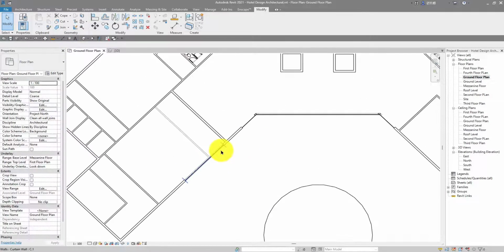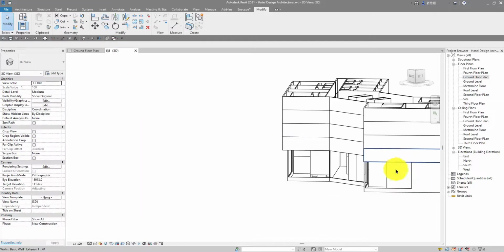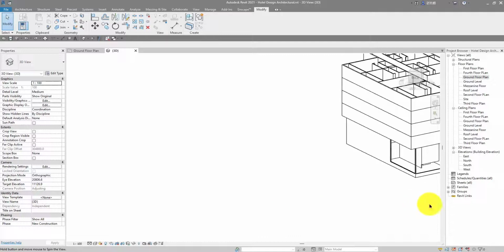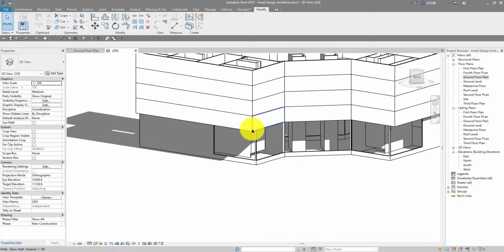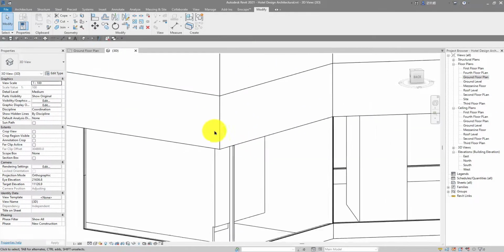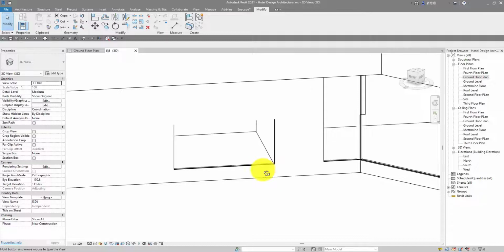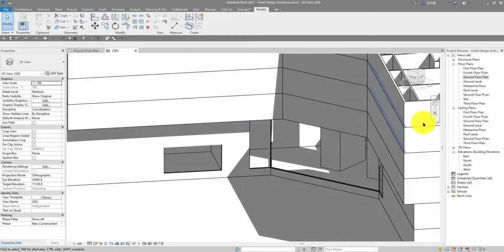So we have that curtain wall created at the back. I was currently at the front, so I had to go to the back, and this is where I created that curtain wall. I had to Control Z to undo that, because we notice we locked in our curtain wall. When we drag this down, it automatically drags with the other one, because we locked it with that symbol that looks like a padlock. We locked it in with that symbol, so we would have to work on this one. This time we want our curtain wall to remain on the mezzanine floor. We don't want it to go into the mezzanine floor, because down there is the ground floor, and that place is going to be like a restaurant.